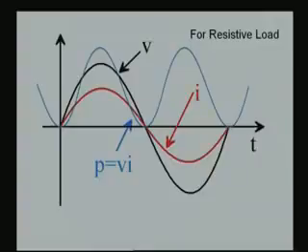So, on multiplication, you see that there is one more waveform added on to the axis, the blue colored waveform, which is the instant by instant multiplication of the voltage and the current waveforms. Notice that at the origin, when the current and the voltage both are 0, power is 0, and gradually the power is positive, rising up, because both the currents and the voltages are positive.